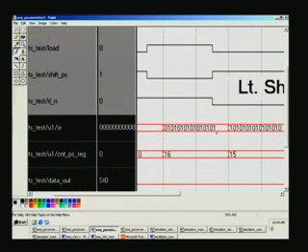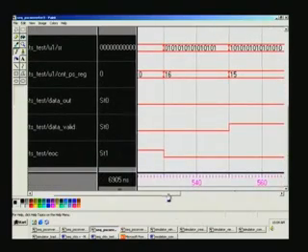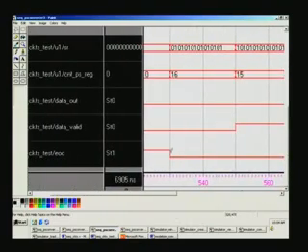So you can see the same 0, 1, 0 pattern here, and once again this end of conversion is the previous end of conversion which we had processed. So the moment you load fresh data, that is reset. So you have to take care of all the intricate details while designing systems, and data valid was deasserted in the earlier cycle.